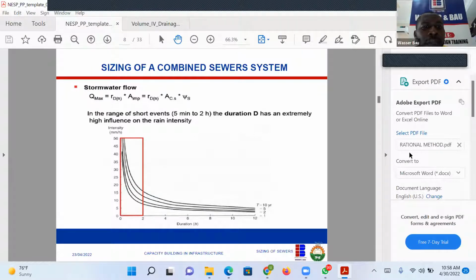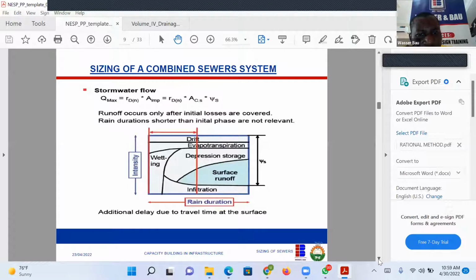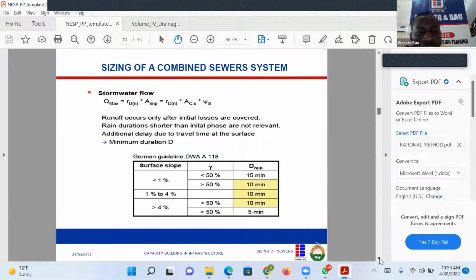Okay. So stormwater again, as we said, is your rainfall intensity multiplied by the impervious area. Impervious area, I can't help but emphasize this. It is not every rain that falls on the catchment that contributes to runoff. It is the impervious area, because impervious area, as the word implies, is impervious to water. So you read it off from here. When you read it off from this design, this is like a case study. Remember this again. When you read it off, you will get a certain value.